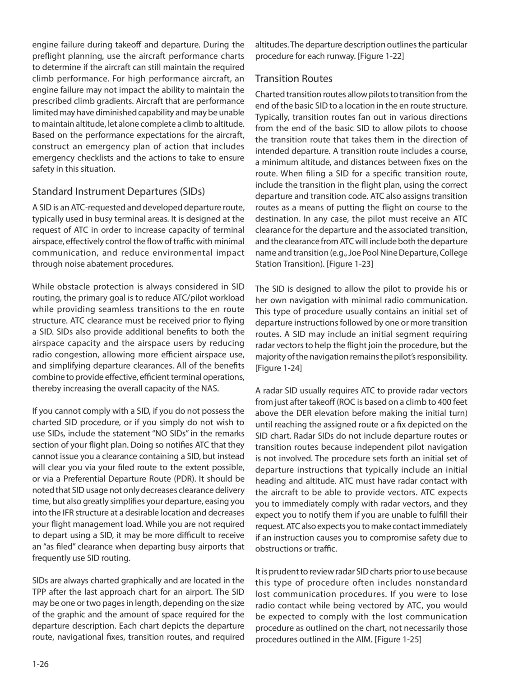Figure 123. The SID is designed to allow the pilot to provide his or her own navigation with minimal radio communication. This type of procedure usually contains an initial set of departure instructions followed by one or more transition routes. A SID may include an initial segment requiring radar vectors to help the flight join the procedure, but the majority of the navigation remains the pilot's responsibility.